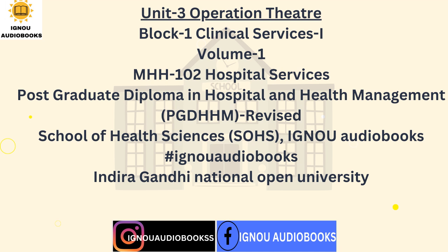The requirements of air supply to operation room recommended by the American Hospital Association, 1962, are as under. 1. Temperature 70-76 degrees Fahrenheit. 2. Relative humidity 55.0% or above. 3. 10 to 20 air changes per hour. 4. 100% fresh filtered air entering from above the roof. 5. No recirculation of air when operating rooms are in use. 6. Positive pressure within the operating room to prevent the entry of air from surrounding areas. 7. Exhaust air taken off from a point near the floor in order to remove dust and heavy anesthetic gases.